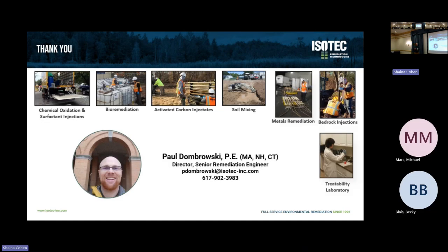Maybe there are ways to put in these wood chip columns at a wider spacing, and that's going to have a much higher hydraulic conductivity, so there is going to be some preferential flow into these columns. But if we inject out of them as well, we can get that kind of distribution of our EVO out of the wood chips. So we have this really long-lasting wood chip, and we get EVO that may fill in those gaps and last 5 or 6 years. That's not a bad combined approach.